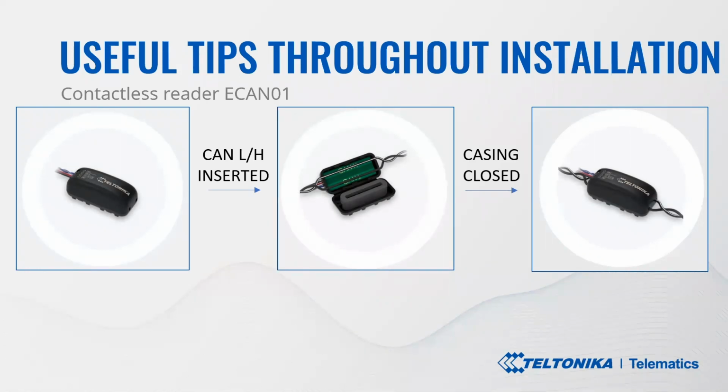However, there is a single disadvantage of this type of connection. When using contactless adapters of any kind, it is not possible to read specific parameters or send request messages to the CAN bus. Therefore, for application with units such as CAN control, it is not convenient because you will not be able to use unlock or lock features.